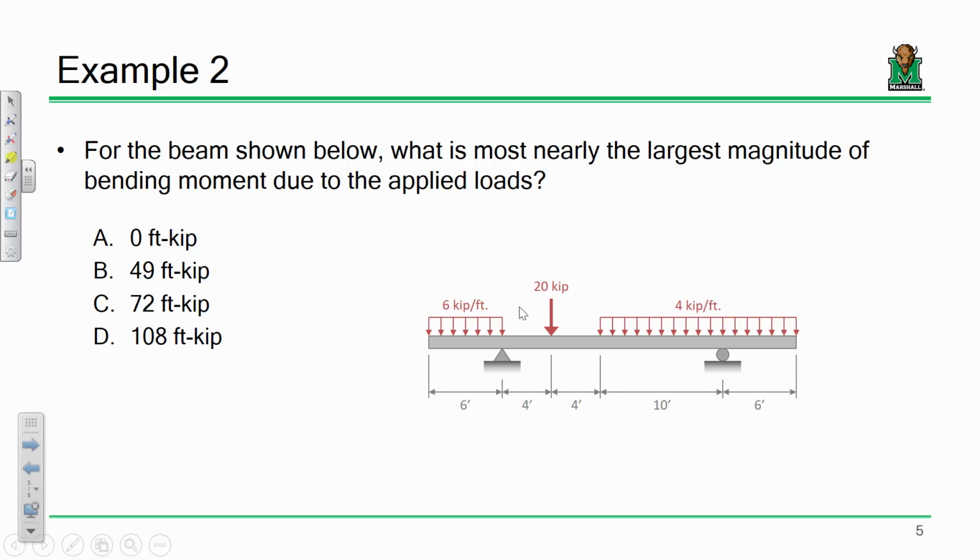And if you get a problem like that, don't draw the shear diagram or moment diagram. Don't do that at all. Just once you get your reactions, cut a section at the point of interest, look either way, and just sum forces or sum moments. Don't go through all the trouble of drawing the shear diagram and the moment diagram because you're just wasting time. But if they ask you to figure out M max or shear max, well, you got to go through it and chug it out.